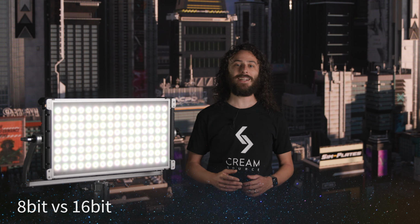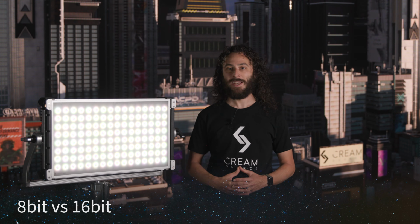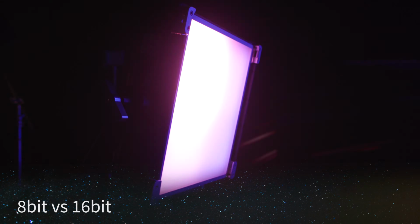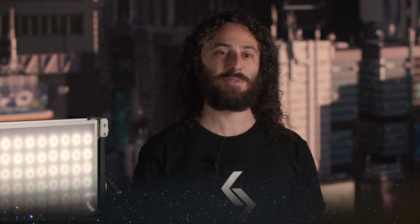Choosing between the 8-bit and 16-bit modes is typically a balance between the level of control you need and any DMX and channel limitations. If you're expecting to do long, slow fades or want to use an XY mode, then 16-bit might be the way to go. If your content is very flashy and strobey, then you may be able to get away with 8-bit. Play around with both and see what works best for you.